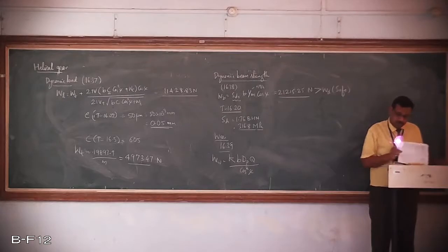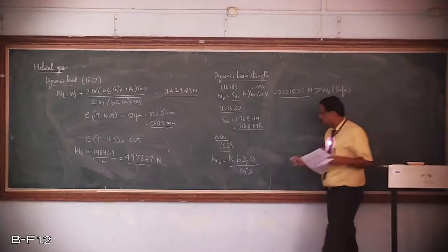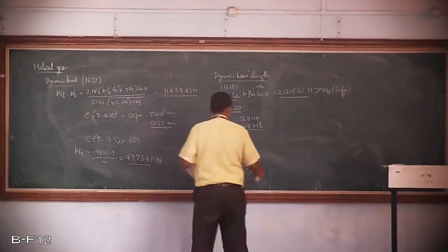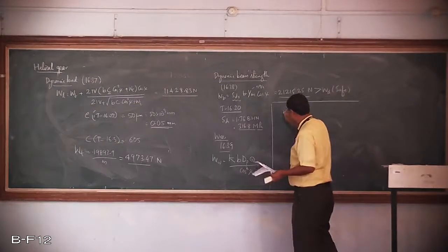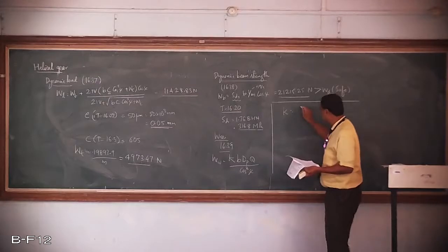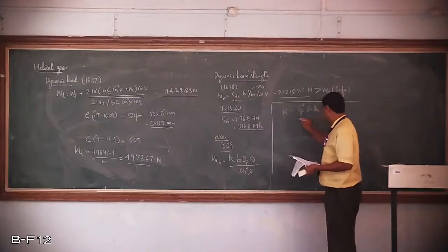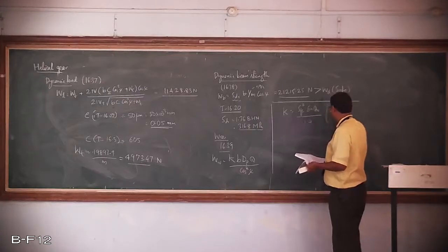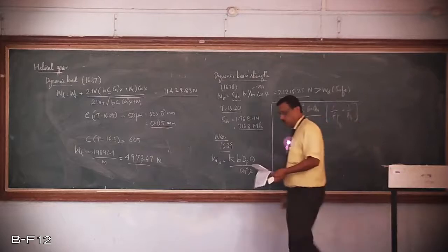Or you can make use of the equation, which is the equation we have in the spur gear. For the wear load, I'll get the value of K here. K equals SFE square, that is surface endurance limit, into sine of phi n, that is the pressure angle in the normal plane, divided by 1.4 into 1 divided by EP, that is Young's modulus for the pinion, plus 1 by EG, that is Young's modulus for the gear. This is the equation to be used.